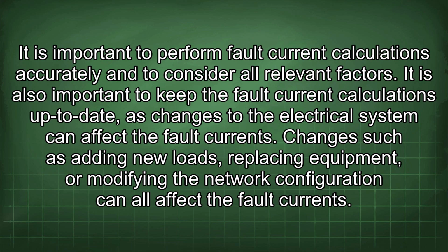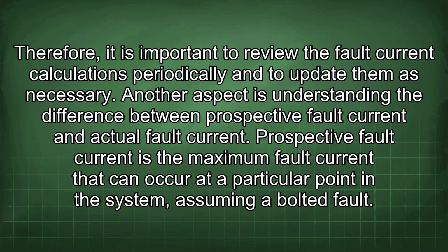It is also important to keep the fault current calculations up to date, as changes to the electrical system can affect the fault currents. Changes such as adding new loads, replacing equipment, or modifying the network configuration can all affect the fault current. Therefore, it is important to review the fault current calculations periodically and to update them as necessary.